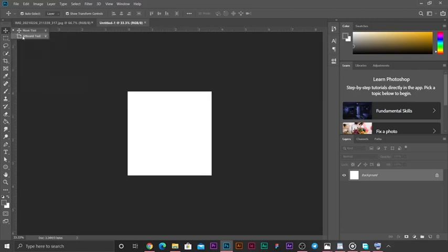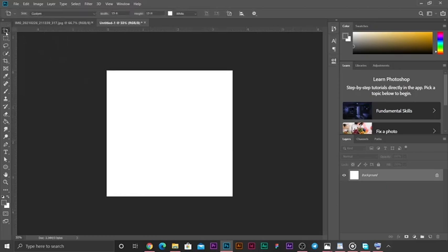I have the artboard tool. So I click on the artboard tool. So once my artboard tool is selected, I come over to the edge of my existing artboard. Then once I'm at the edge, I'll just double click and drag to the opposite edge of where I started my selection from. So when I get to that point, I release my hand.